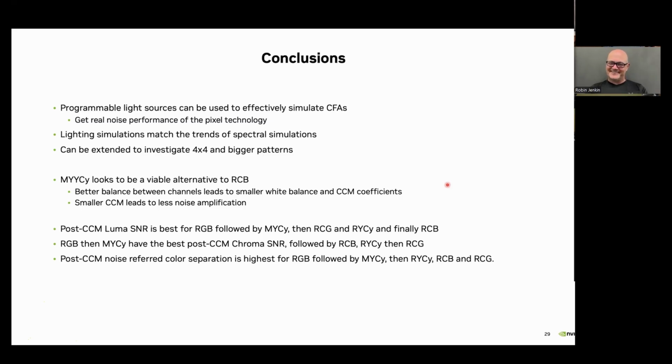Right. I've done the same analysis at a much simpler level just to make the proof of what you did, that at the time it was really the clear pixels versus the RGB. And it's easy to prove that the clear pixel is not your best friend, mostly because of the matrixing and the channel disparity. I was going to say, I think I know the answer, but for the numbers that you reported, those also include the white balance gains. In addition, when you say post-CCM, it's post-white balance CCM, so the channel gains are included as part of the noise amplification. Is that right?